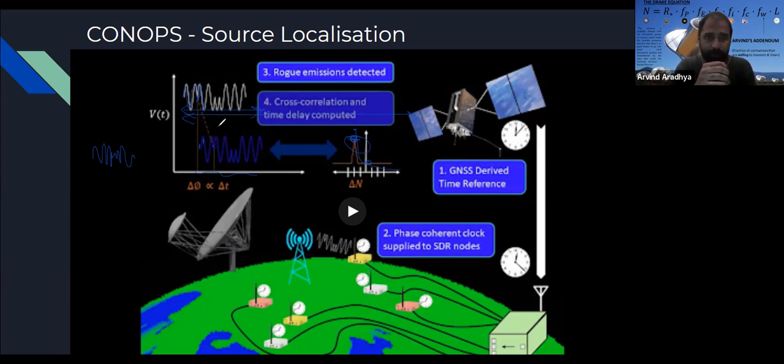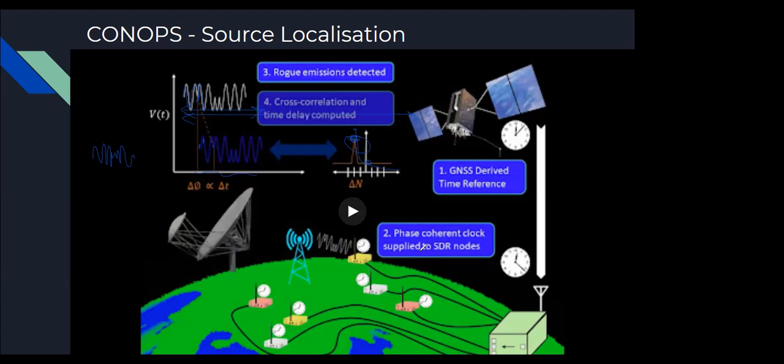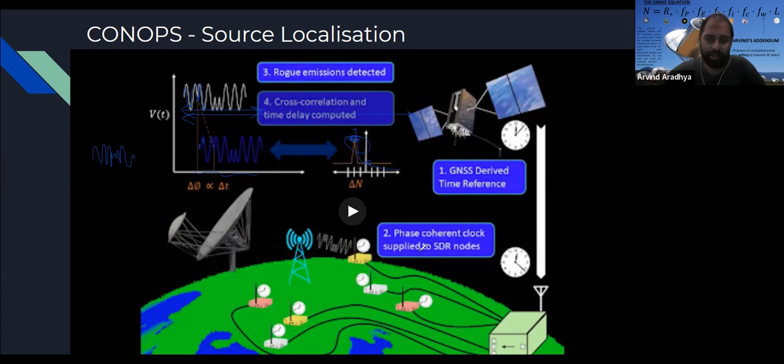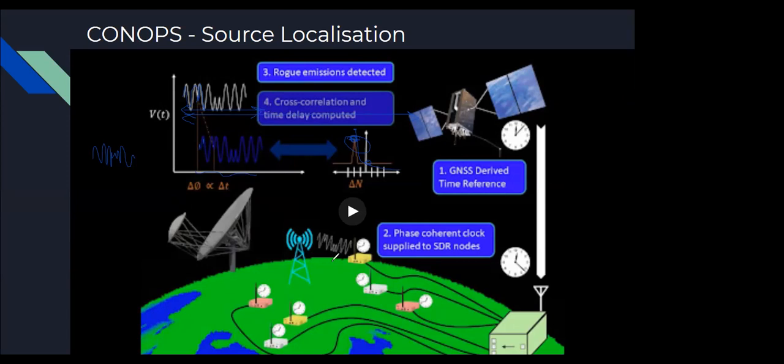Sometimes we do it in the frequency domain as well with a spectrogram, and that is another added step of computation. So when I say real time, it's really near real time. On the site for the lightning maps, you can see that it's delayed by about 10 seconds. So it's not like hours. The entire point of this is to be able to detect someone who's transmitting within about 10 seconds, and then call them up and say, okay, look, turn your phone off or something.